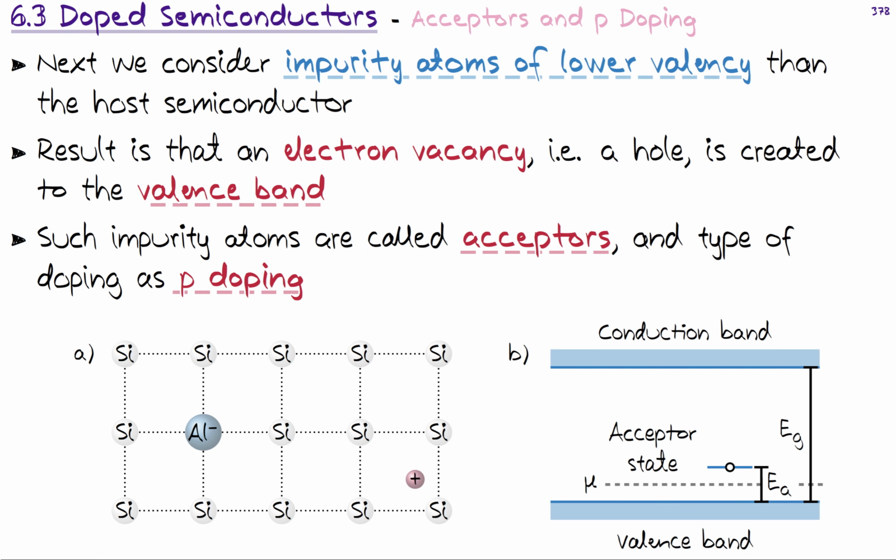Here is a picture that highlights what happens. We are, for example, considering again a silicon lattice. Please note, silicon of course forms a diamond lattice, so an FCC lattice, which has two silicon atoms inside the basis. And we add aluminum into the mix every here and there. We dope it slightly, and at the end of the accommodation of aluminum into the silicon lattice, we will have positive holes nearby that can readily move around. Basically these holes will be residing in the valence band.